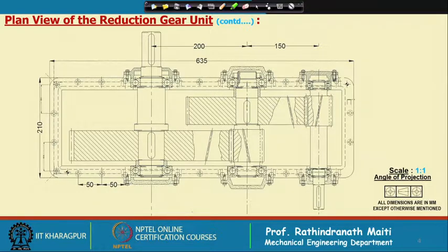With bottom base it will be slightly more, which we can see later in the complete drawing. But this is a very small size gearbox. If you calculate the power with nominal torque, it is about 2.753 kilowatt, and as there is 200% starting torque, maybe we can select a little higher size motor, but this is really a small size gearbox.